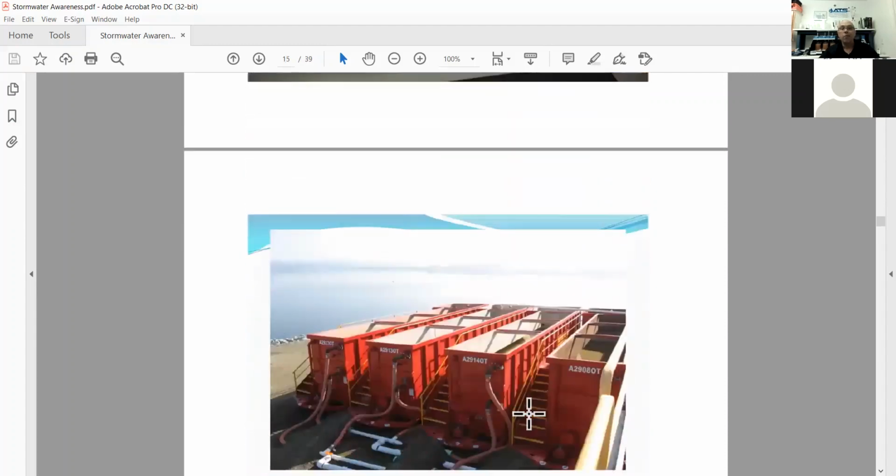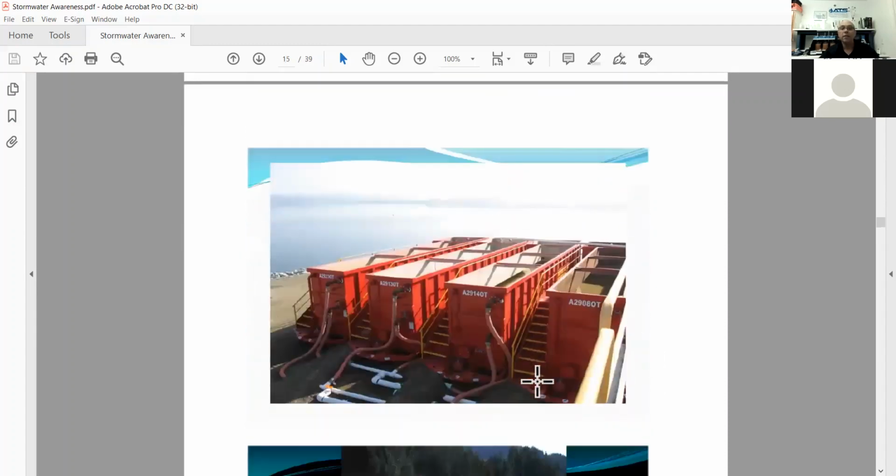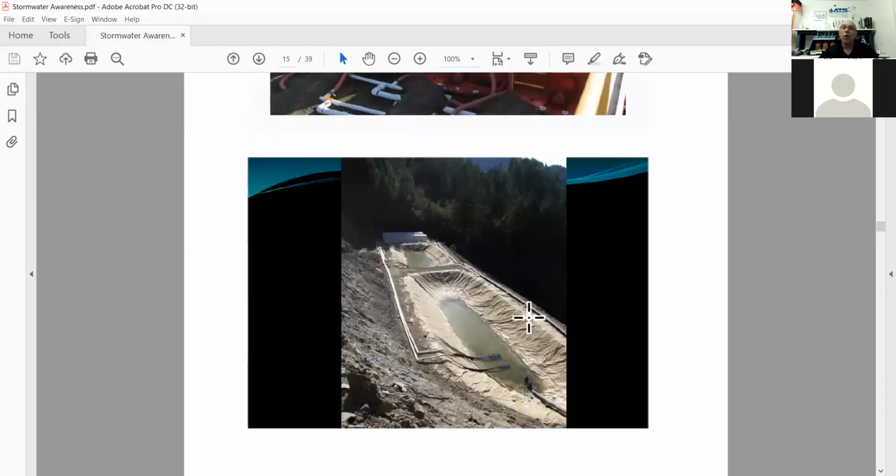We have some tanks here and basins, and notice the oval shape here. And notice here that the contractor, when they were building the basin, made one error. We put pumps here, they put the influent here. The ideal situation here was the influent would be here, and the water would flow across with settling to the pumps. So a slight error made here, but it was workable because of the second pond.